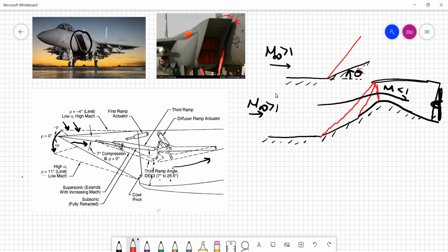This gap is to compensate for the boundary layer growth on the aircraft. We will see what a boundary layer is in this class, but a boundary layer grows on the surface and has a certain thickness when the flow reaches the inlet position. Since boundary layer means low momentum fluid, we don't want that low momentum, low kinetic energy fluid to be fed into the engine.